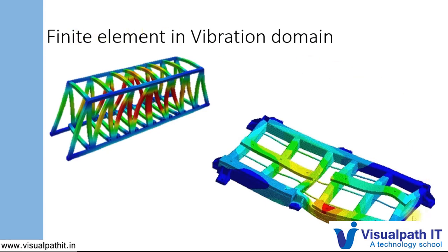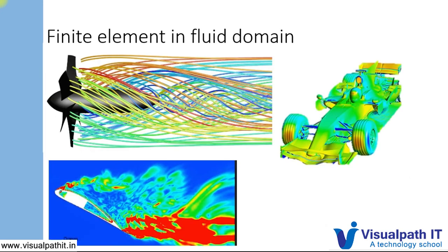So we will be using finite element extensively in the vibration domain to understand the response of the system, the stresses that are getting generated in the system, or whether the system is going to get excited because the natural frequency is coinciding with the excitation source. Something like that we will be using to anticipate the failure of the system due to vibration.